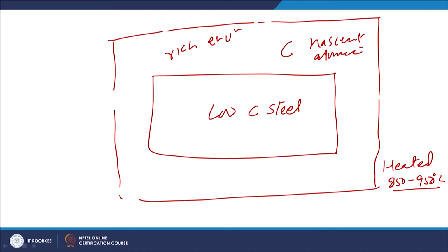Heating of the component in the carbon rich environment at a high temperature leads to the active diffusion of atomic carbon from the surface to the subsurface layers of the component, and this happens due to the concentration gradient of carbon from the environment to the component. The high temperature facilitates three aspects.